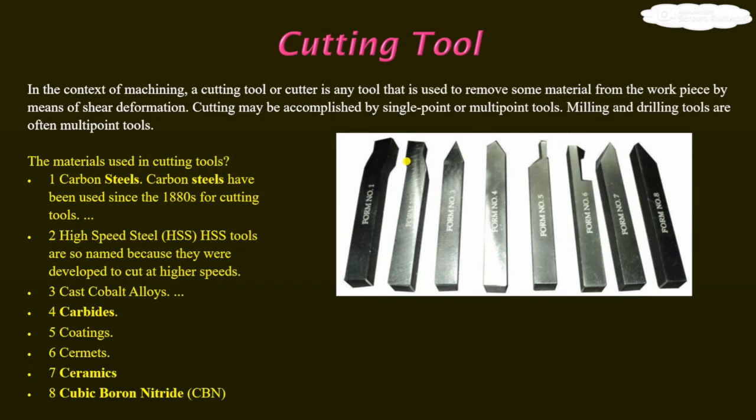We know that there is friction between the cutting tool and the job. If it is not hard enough with respect to the workpiece material, then there will be a fast damage of the cutting tool. That's why high carbon steels can be used as the cutting tool. It is the material property that if the carbon percentage increases in the steel, then it becomes harder. Another most important property of the cutting tool material is that it can withstand high temperature.